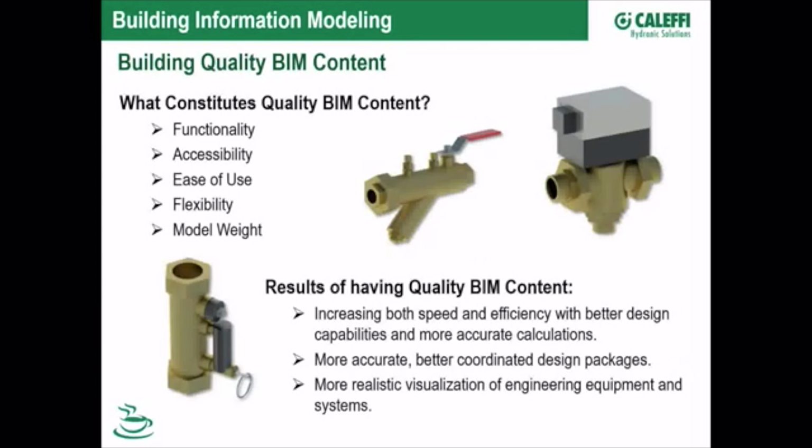Model weight. Some manufacturers just want to import their SolidWorks or Inventor models directly into Revit, because why would they want to recreate the geometry if they already own it? The problem with that is when exported into Revit, the file size tends to balloon for the family, and it doesn't really sit well inside a project. Who cares, right? But at the end of the day, if you've got 1,000 instances of an item within a project, and they use the true geometry from SolidWorks, your regeneration time is going to balloon. It's going to increase exponentially.